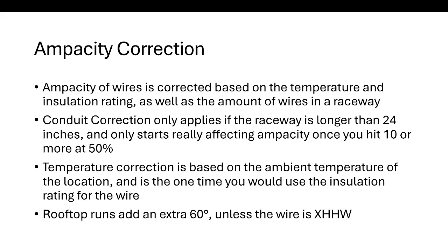One thing to note that is not on here, the ambient temperature is based on, I think, about 30 degrees Celsius, which I think comes out to about 80-something Fahrenheit. If your temperature goes below that, you don't start rating your conductor for more amps than it's rated for already. It only applies if you're going above your standard ambient temperature.